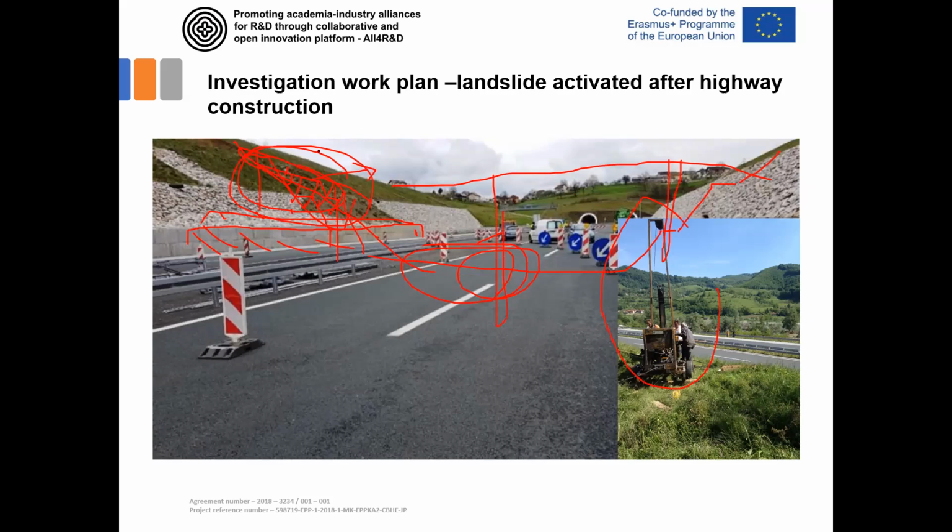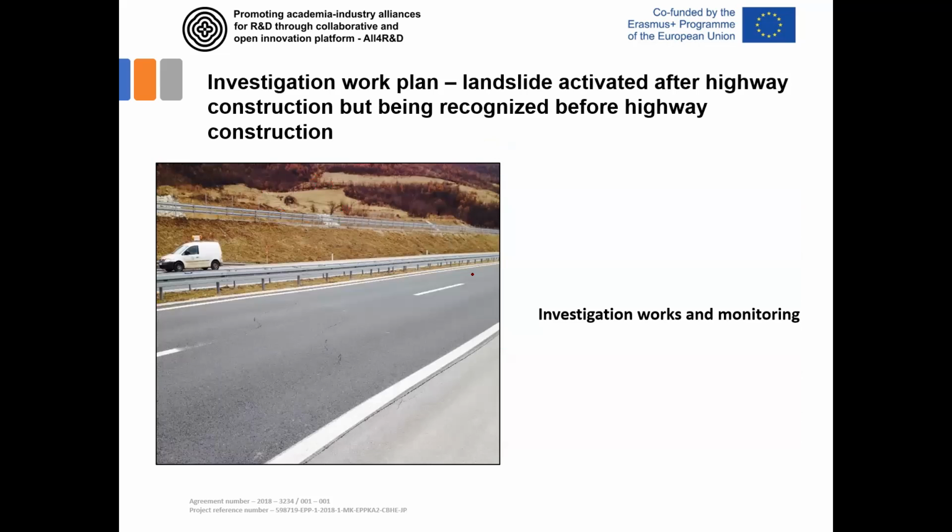Usually, failures like this happen due to infiltration of surface water. Infiltration of the surface water is usually the main cause of these so-called shallow slidings that are 3, 5, or 6 meters deep. But these failures can bring a lot of problems to the existing highway route.